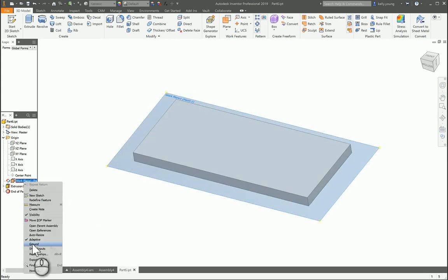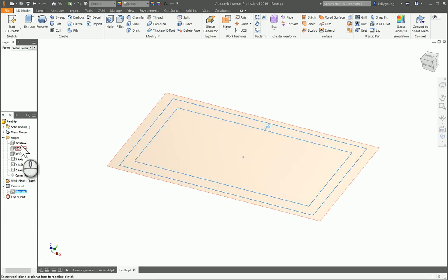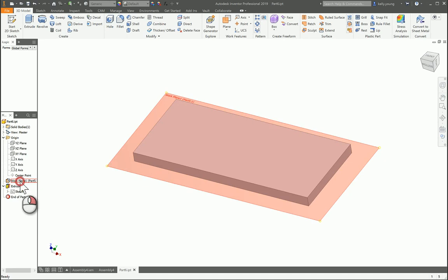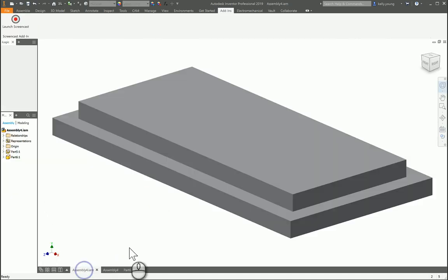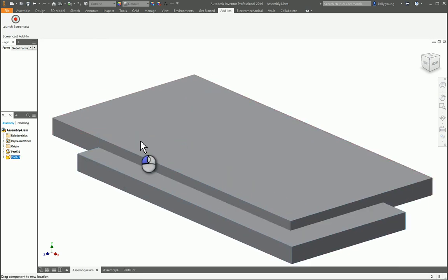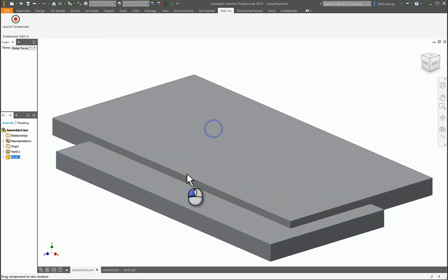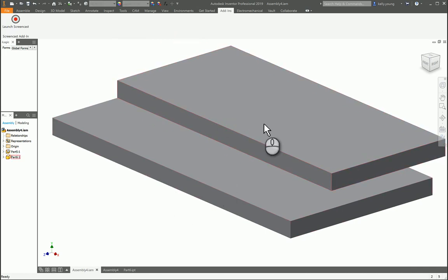So if we ground it again, the best way to do it is come back into here, right click and say redefine to the home plane, and then you can come into here and delete that because it's no longer a reference. Problem is, if you come back into here, now it's basically disassociated because it's not adaptive, it's not locked in, it's not constrained. So any reference to anything else. So anytime you do that, you'll basically have unconstrained sketches. It won't be on the origin plane. You'll have more problems. That's personally why I don't use adaptivity very often.